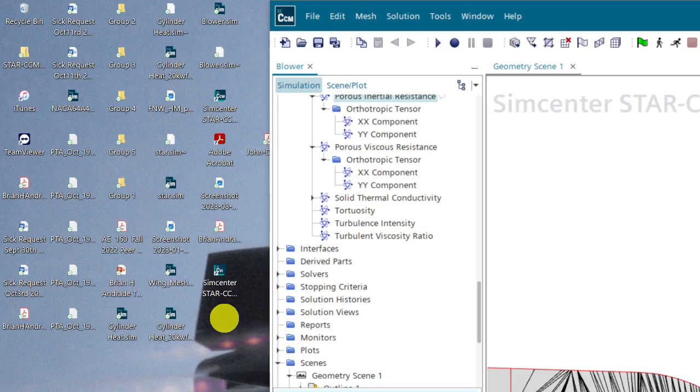Because if we make it literally impossible for it to cross here, that can make your simulation numerically unstable. So we make it possible, but only a little bit, if that makes sense. The flow will, again, once it's fully converged, just be following the y direction. But it's allowed to follow the x direction temporarily to figure out what's going on.